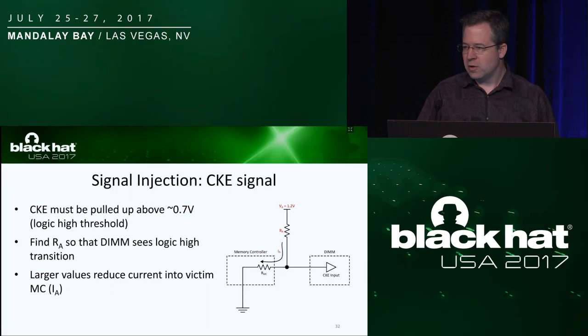So what we found to start our attack was we had read through the JEDEC specification about how we expected the memory to work, and we took our system into the lab and essentially went through validating our assumptions about how the DIMM worked, as Anna had just described. So we went through each one of the 288 pins on the bus and tested out what was the logic state and what was active and not active on that pin, both during S0 and the S3 state, which we were most interested in.